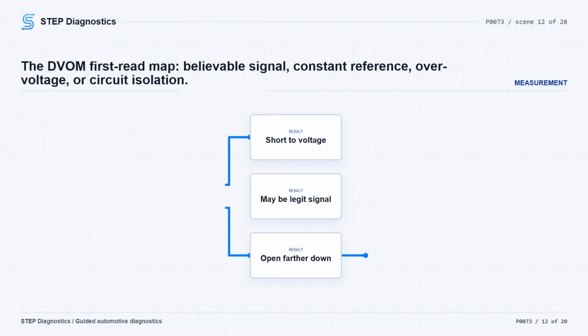If you are using conventional voltage testing, make sure the temperature sensor and ECU harness connectors are connected and locked before backprobing. Turn the ignition on and measure the temperature sensor signal circuit at the sensor harness connector. If the signal is between 0.1 and 4.9 volts, the sensor signal may be a legitimate reading. If the fault is active and scan tool voltage does not match the meter, the ECU is suspect.